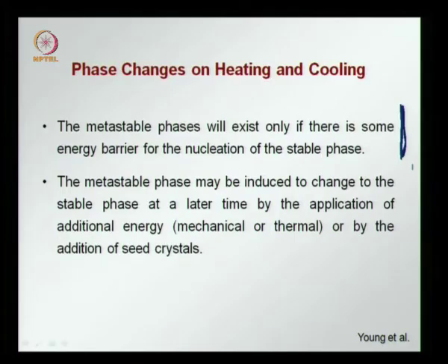The metastable phase can be induced to change to the stable phase later by the application of additional energy. This can be mechanical or thermal energy or by the addition of seed crystals, otherwise it will always be the stable phase, because the stable phase requires less energy than the other phase.